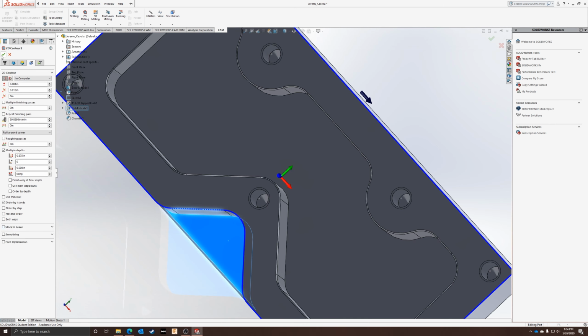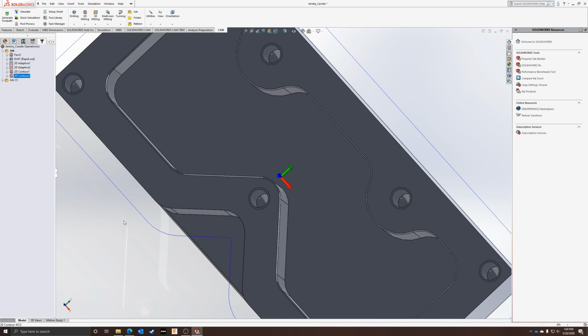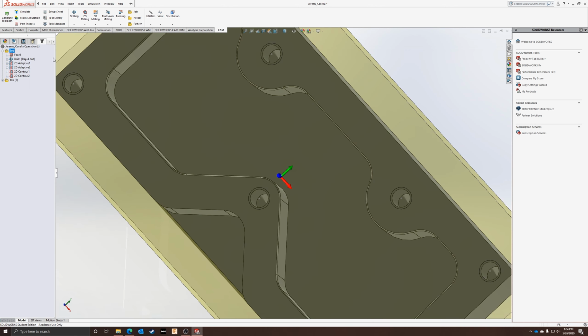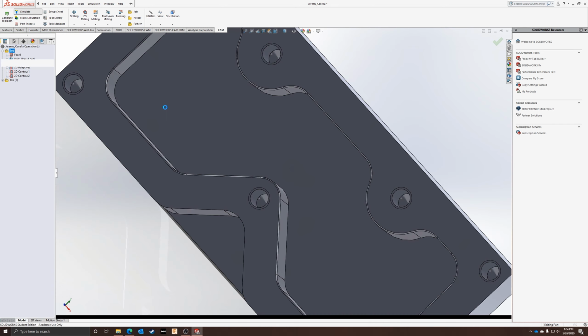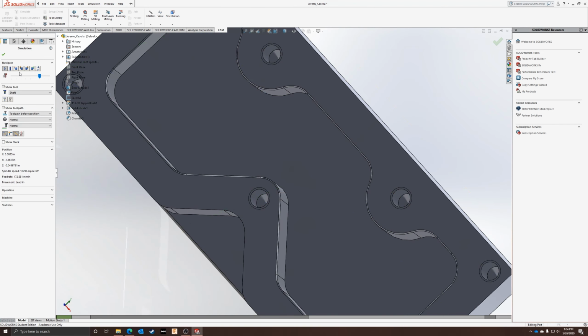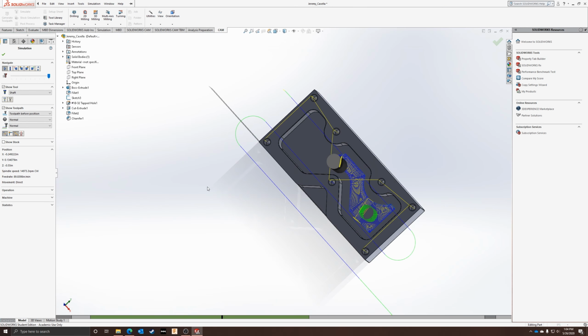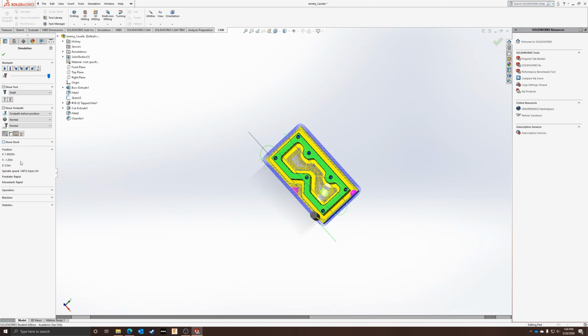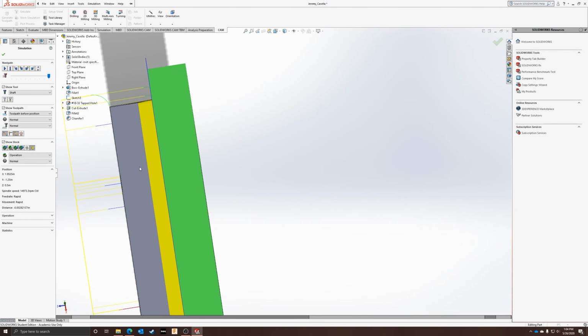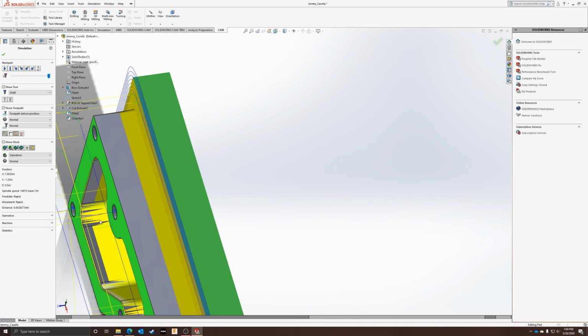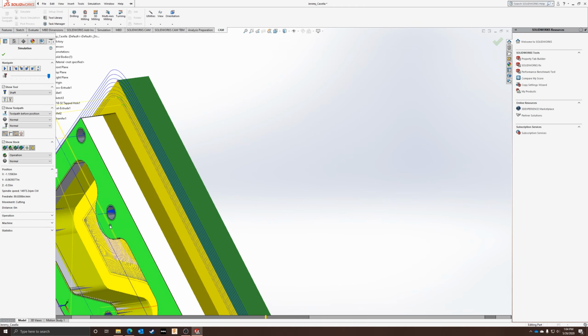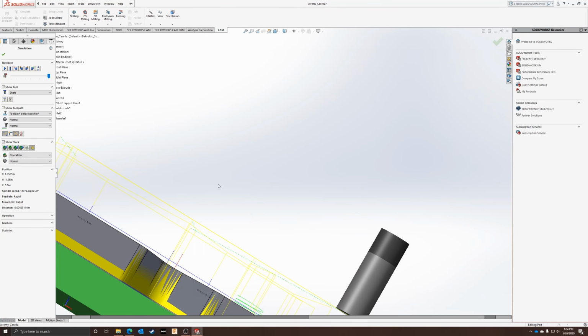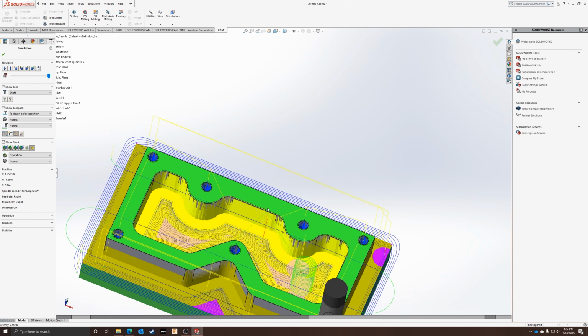So if I do that for all this, and once again, the rest of these settings in this menu are entirely contextual. If I run into an issue when I'm machining, I look into those to fix it, but not when I'm starting out. The more you mess with it, the more unexpected things might happen, right? And so now you'll see that there's a perfectly machined surface there. It's like glitching between rounded gray for the part and yellow, which means it's right on it, right? And so it's done. We've done everything. Now it's a completely machined part. All we have to do is tap it and take care of the backside, which we'll talk about in a second.